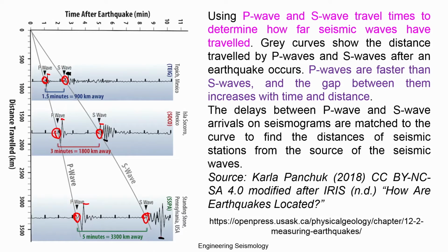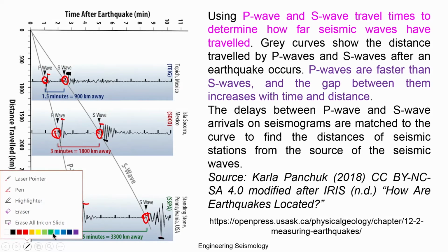Second, the amplitude. For the P and S wave, generally the P wave we do not consider as an amplitude required for the peak ground velocity or displacement part, only the S wave part we consider. Generally the P wave amplitude will be much lower than the S wave amplitude. So, you can see this amplitude, this amplitude, these values of the amplitude also keep changing. Second, you can also look at how much time the S waves are repeating, that also you can see.